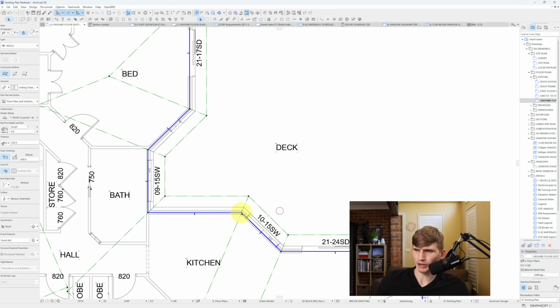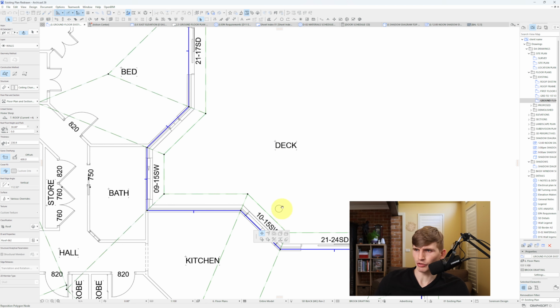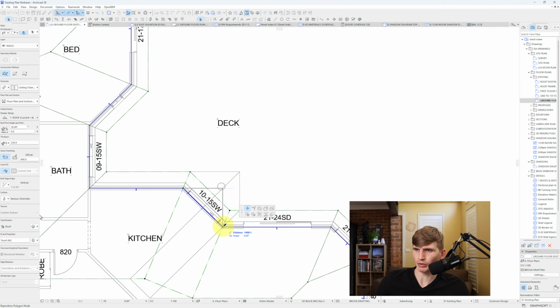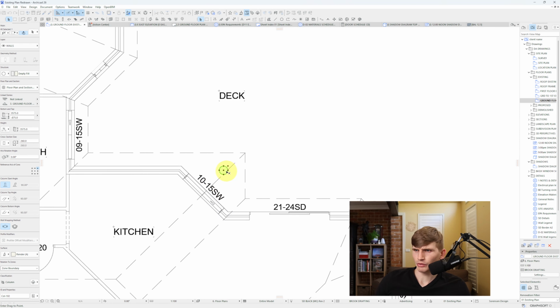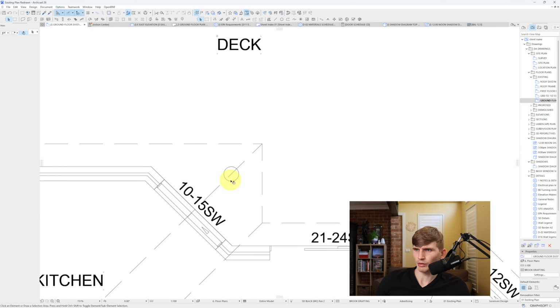So I'll grab this roof plane. I'll pull out the pitching point until it's in line with this part just here, holding in shift. And then I'll click this node over the top of this node. And there we go. That straightens up that roof just there. I'm just going to drag this post until it's centered to that point just there.